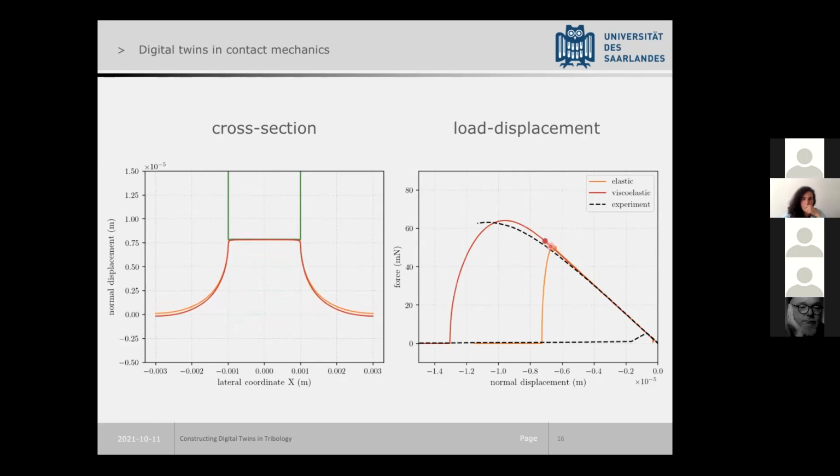And what you get to see is that basically when we move quasi-statically without viscoelasticity, the contact breaks at this point. And what happens is that it takes a very large force to propagate the crack. So in reality, you have crack propagation when the contact breaks. And in viscoelastic systems, where the difference between high and small frequency modulus is very different, there is a whole lot of dissipation that is going on in here that we need to capture.